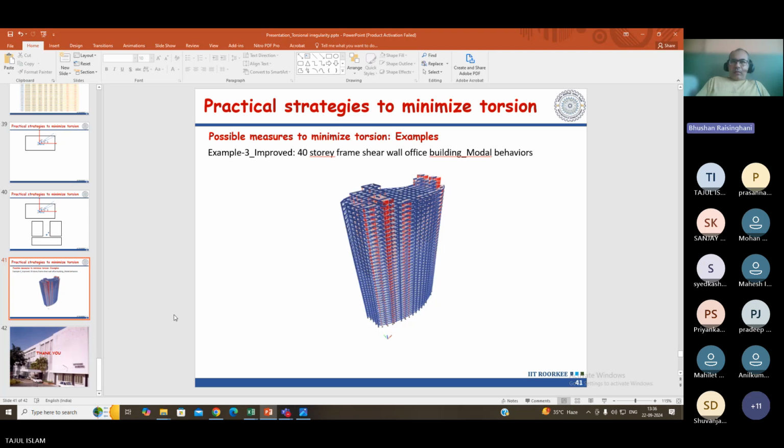What happens is that the column has a shear modulus G, based on which the stiffness in the twisting direction gets introduced in the software, and that converts the twist into shears. So this effect you can see mostly in the shear force, and that shear force will lead to the additional moment. Whether that is correct or not, we don't know.